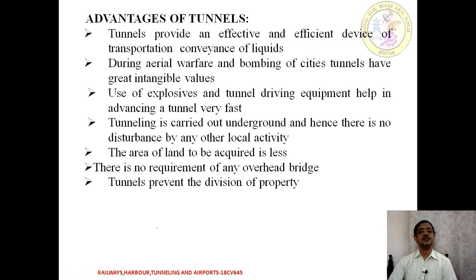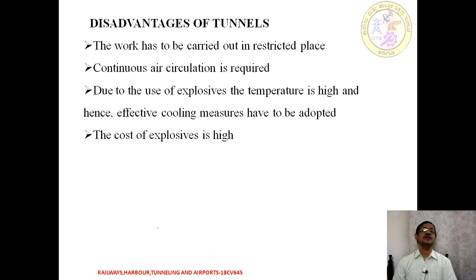Also, from the safety point of view with respect to warfare or bombing. The use of explosives and tunnel driving equipment helps in advancing the tunnel in quicker phases. Tunneling in the undergrowth causes no disturbance to local activity. So, that is one more advantage we have. There is no requirement of an overbridge, and also tunnels prevent division of property, as in the case of a bridge or anything else, where property gets separated or divided. Next are the disadvantages.